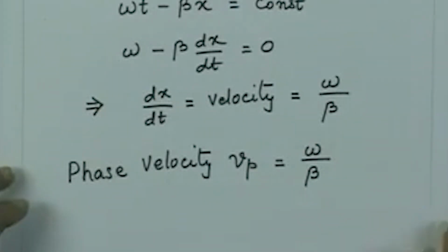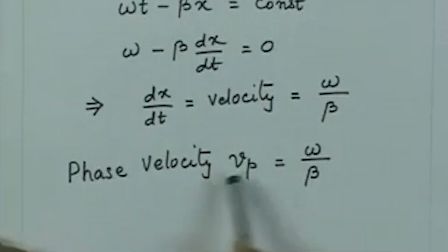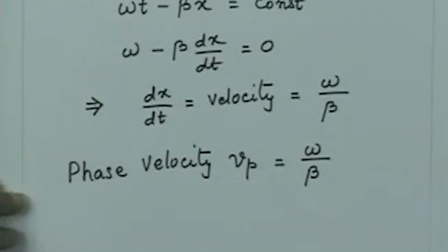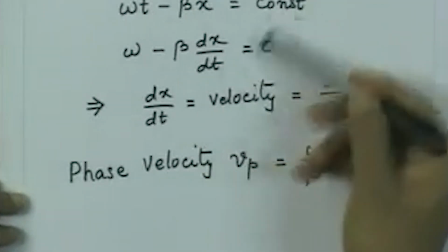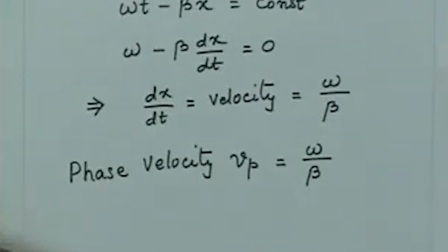So essentially knowledge of the propagation constant or the phase constant is important, because that tells me the velocity of the phase of the electromagnetic wave when it travels in the medium. In fact, for a traveling wave this is very straightforward. So I get a relation which is like this. However, the concept of phase velocity can be extended to any arbitrary wave propagation.